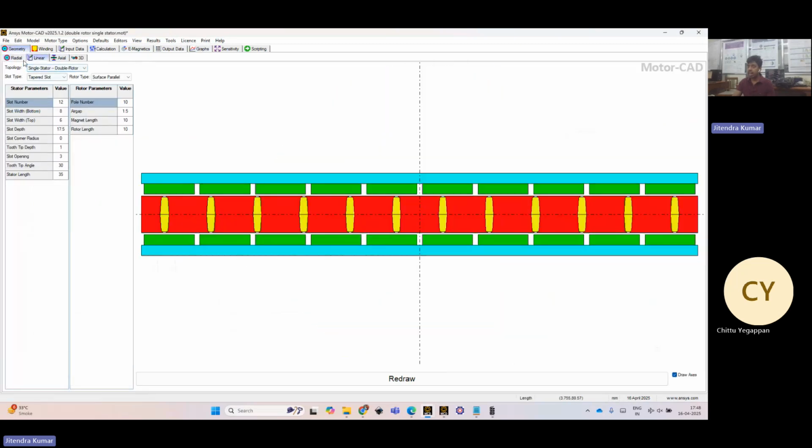It has dual air gap. One thing, to maintain the same air gap flux density per pole, because in a pole there will be two air gaps, and both the air gaps have to be dense equally. While maintaining that much, you will require more magnets. So here you could say, I would not comment in terms of quantity, but it has been almost higher than the radial machine. So that is one drawback.